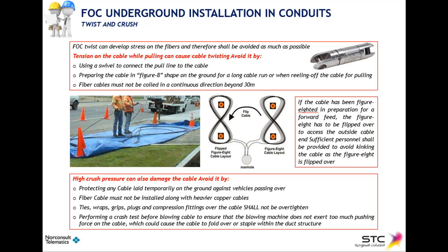Now we are going to see some techniques to avoid cable crushing. Basically, you have to protect the cable. This is the rule of thumb. If you are installing cables temporarily, or probably this type of installation is only temporary, crossing roads where the vehicles are passing over, you have to protect that cable.